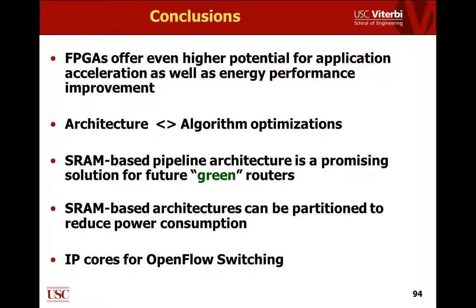Our interest is driven by looking at these kinds of fine-grained devices and then exploiting various architectures on top of them. By architecture, I'm referring to building some kind of a virtual architecture on top of the FPGA architecture, and that virtual architecture maps nicely into the physical hardware, and that gives you high performance. And then we do a number of optimizations by using the memory effectively. The memory here refers to the distributed RAM or the block RAM in these devices. And most of the power that is dissipated in these devices is in storing and accessing these routing tables as tries or tree structures, and then we control that power, and that gives you higher performance in these implementations.